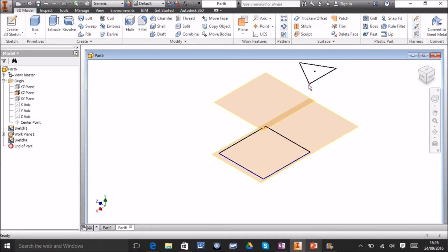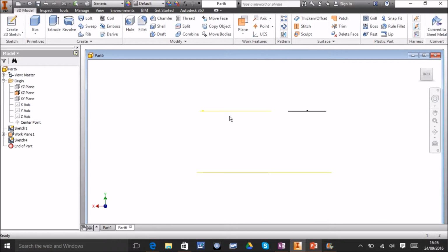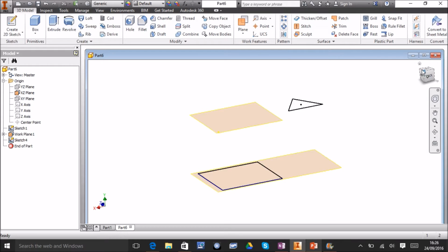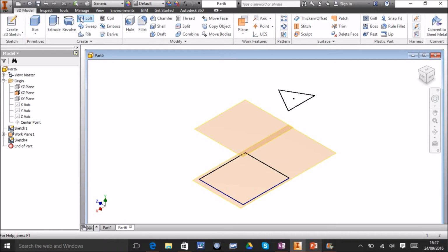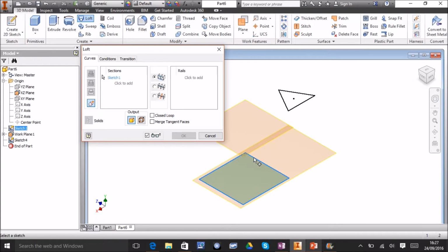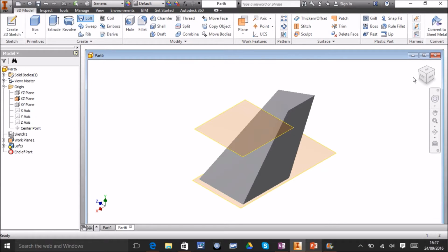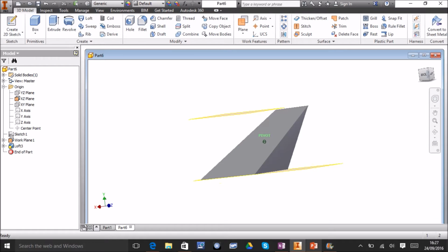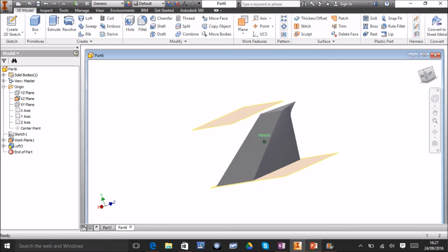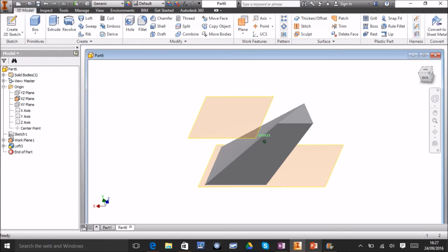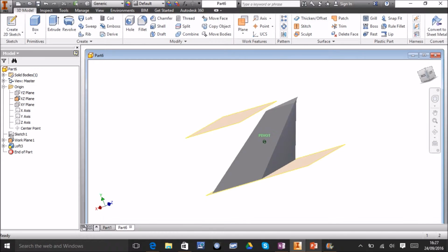So this time the shape that we are lofting to is a lot further along than directly above our first shape. So when I click loft this time, and I loft between the square and the triangle, and click OK, I get a much more complex form. Okay, once again, we're changing the shape, we're changing the size, but we're also changing the direction.